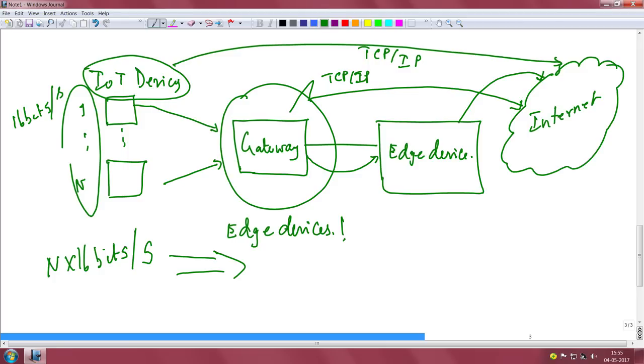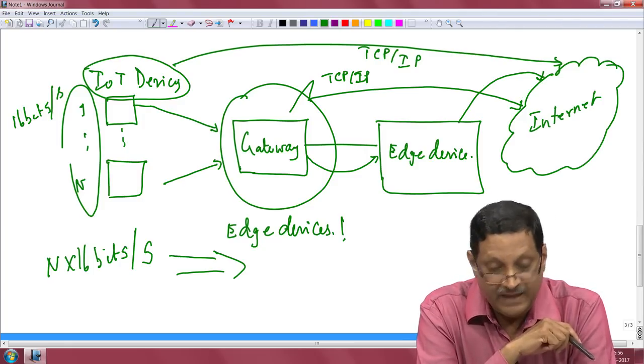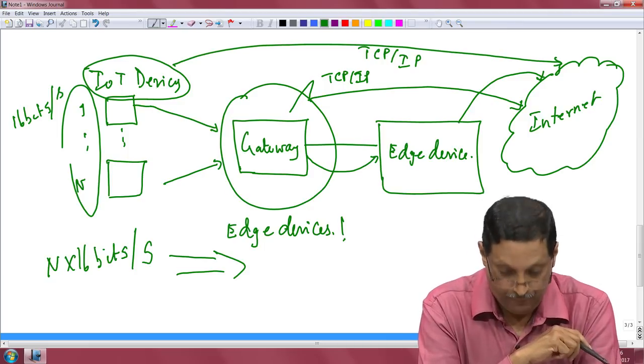Therefore, you can see now that IoT devices, often because of their memory constraint or processing constraint or any one of these being constrained devices, are unable to talk standard protocol, which puts the pressure on the gateway to do a simple protocol translation of taking data from these IoT devices and putting it out on a protocol well understood over the internet LAN. Very good. So this is one very nice function that the gateway can essentially take responsibility of.